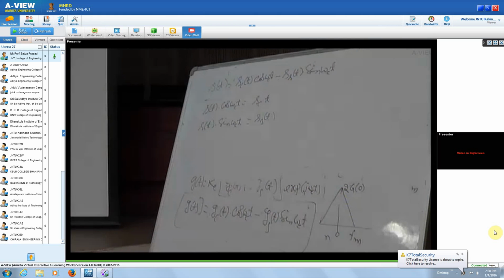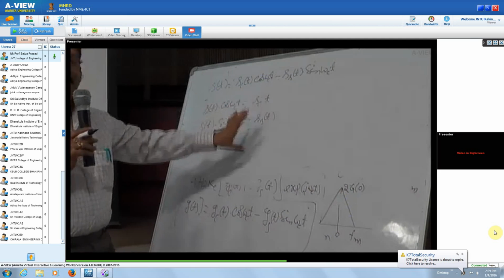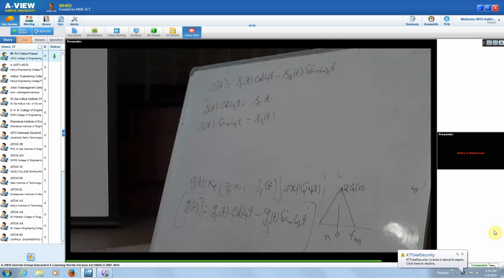But basically it is proportional to your in phase signal and your quadrature signal. So we want to find out this Sc of t and Ss of t in terms of your LSB or USB signal, so that we can represent our overall band pass signal in the time domain derivation.